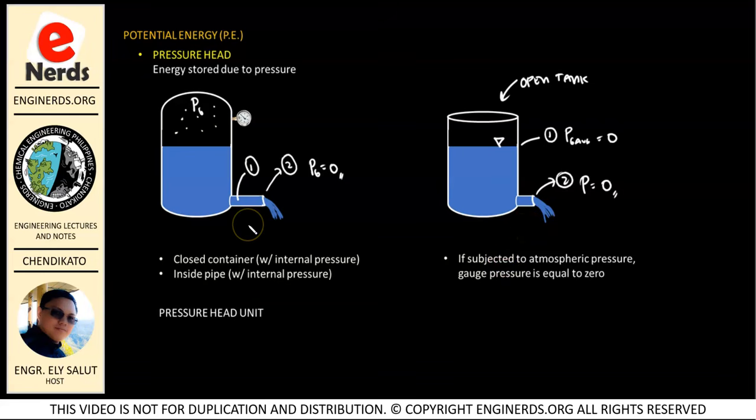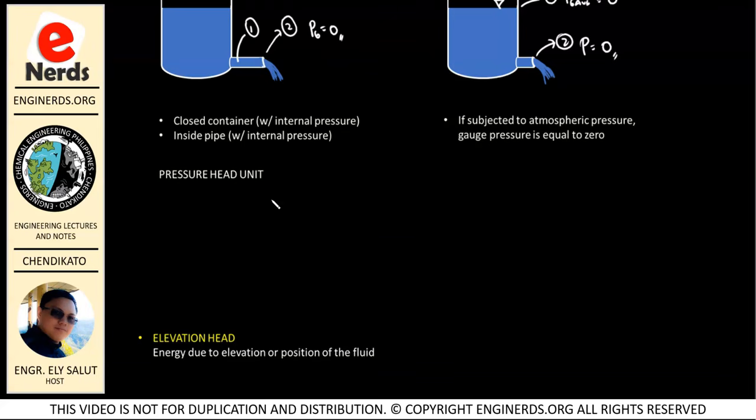So you have to remember that kapag nakaka-encounter kayo ng triangle dito sa ibabaw ng ating surface. Okay? So sabi natin kanina, if we are dealing with pressure, our unit is in kilopascal, di ba? So kailangan natin makuha is yung pressure head, which is in meters. So how are we going to convert our units? So alam natin kanina, when we are working with Bernoulli's energy equation, we are not getting energy, but we are getting energy per unit weight, di ba?